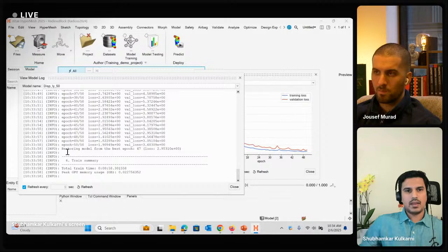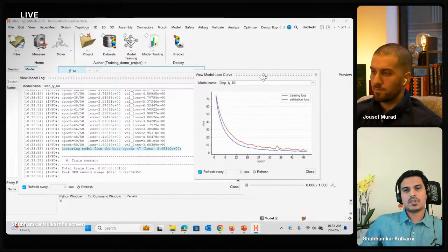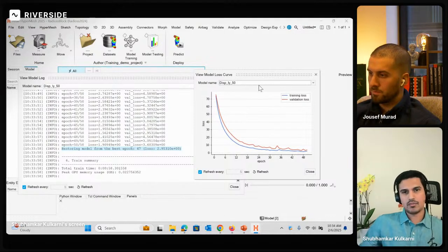And if you look at the log, it also summarizes the best epoch. So physics AI remembers the best configuration or the best training round of epoch. So you could run it for a really long time if you're not sure how long to run it, and then physics AI will automatically cut back to the best epoch it encountered during training.